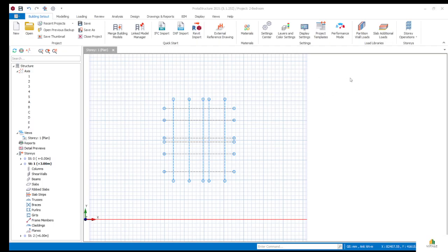Then similar story. This is what I want us to do, because we want our columns in story 1 to be the same as those in story 2. What we are going to do is hold your shift and select the story 1 row at the similar story column. You select it, it will show something like light blue. Then you hold your shift and drag it down to select the other story in that similar story column.